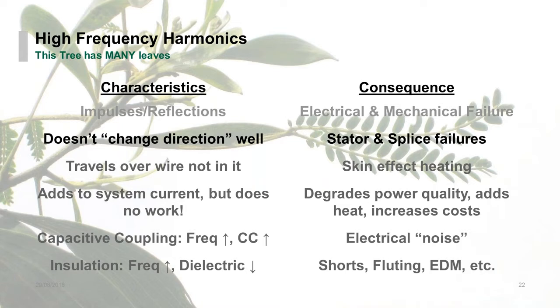And if it's going around tight corners, as in a stator of an electric submersible pump or other types of motors, then you'll typically see some kind of stator failures there. And then also in splices, because it wants to reflect there, back, and you get the amplification because those waveforms start adding onto each other.